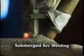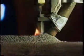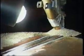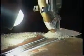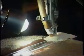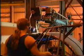In submerged arc welding, a bare, continuous consumable electrode wire, shielded by a layer of granular flux particles, sustains the arc. When the arc is struck, the tip of the electrode is submerged in the flux, and the arc is not visible. Welding proceeds without the intense radiation that characterizes open arc processes, and with little fumes. The submerged arc welding process varies from semi-automatic to fully automatic.